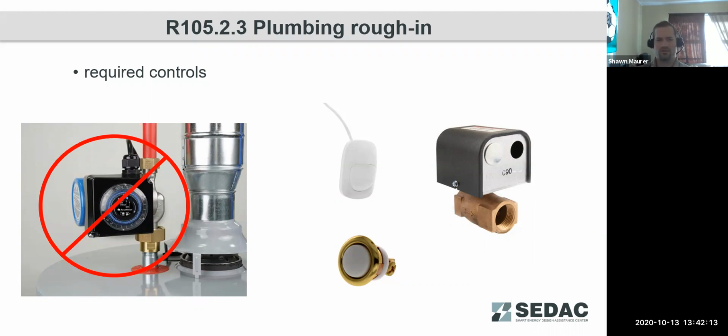What we're noting here is you could not have just a timer on a pump system mounted to that water system because it's not indicating when there's a demand in that residential facility. So you would have to have a flow sensor mounted to the cold tap inlet to the hot water tank. It is the best place to install that to detect when hot water is being called for in the building, and that tank gets refilled then through that cold tap inlet.